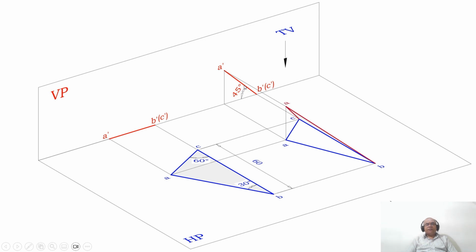In the image, when you look from the front view, the image is also getting rotated in the front view. Once you rotate at 45 degrees, which line are we rotating? I am rotating this line here. Therefore, with this as center, taking the radius of this, cut an arc on this, and mark that point as A dash, this point as B dash, and C dash in bracket. Now, to this I need to write the top view.